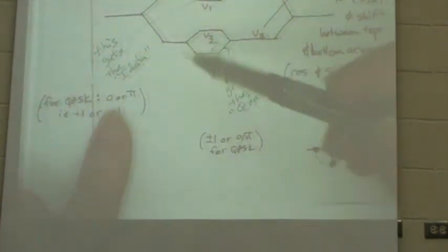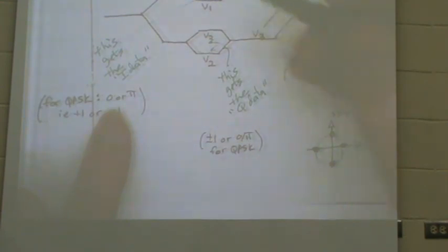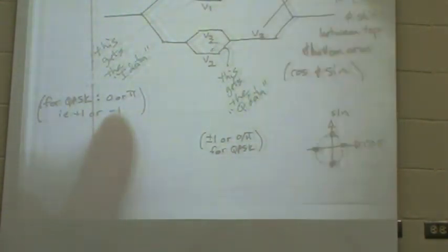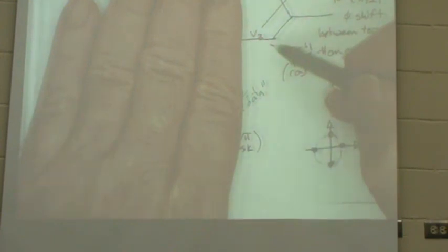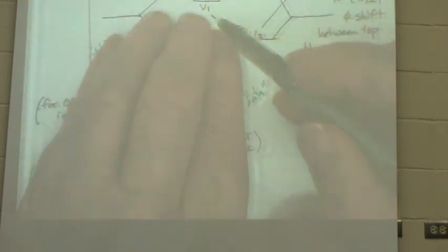But what do you think? I can make this phase shift anything I want. I can make this phase shift anything I want. But if I've already set these two to be sine and cosine, then well, what about making this V1 and minus V1? Then that little box there becomes an on-off modulator. Okay. Can I do 4 level with just on and off?